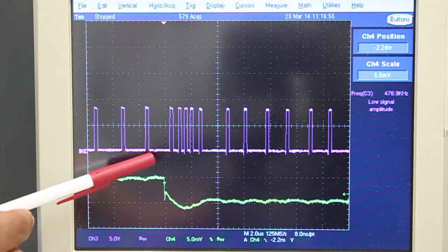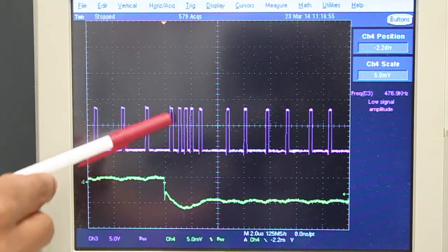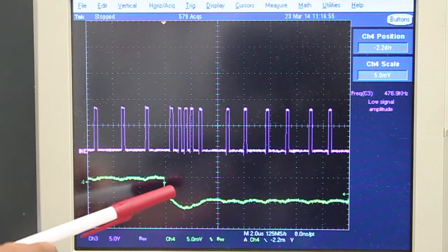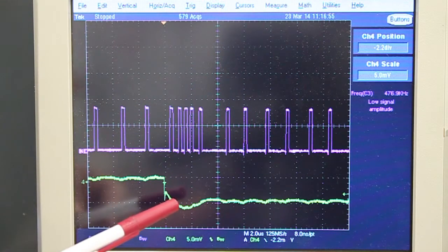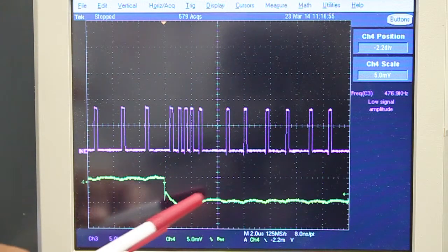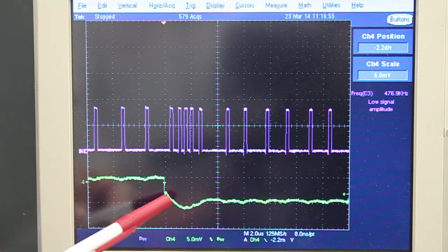Here in this board, in the constant on-time control and single phase operation, you can see in the load step up transient response, the pulses come very close, and we actually reduced some output capacitors in the board. For that reduced number of caps, we can see some undershoot here at the output.